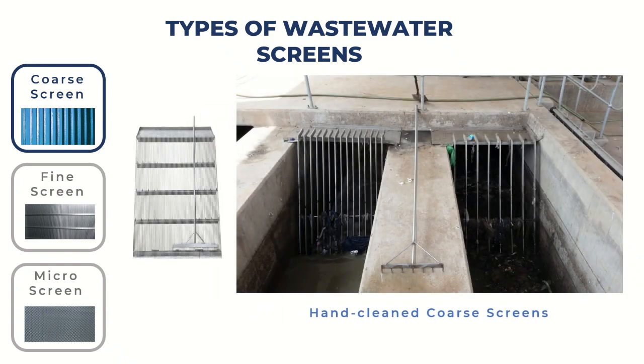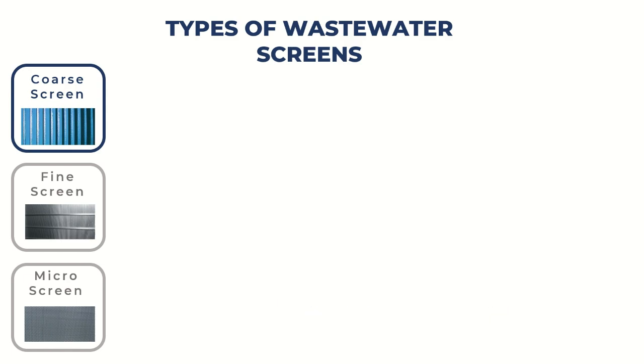The hand-cleaned coarse screens are utilized in smaller wastewater treatment plants and facilities where the wastewater is hand-raked. This system is perfect for backup when it is a high flow time or more advanced, and the machine-operated screening method is not functional due to repair or maintenance.